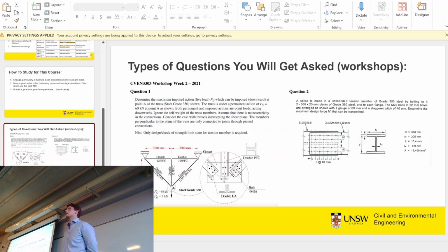Shear, or is that something else? Not quite shear. If I had two members like this, shearing would be like putting a point load on that member. But if I'm pulling the members apart, and say the bolts are infinitely strong, so they're not going anywhere, they're fine. If I pull those tension members apart, what will happen to the bolt holes, do you reckon?